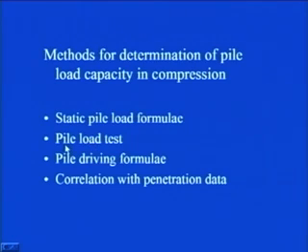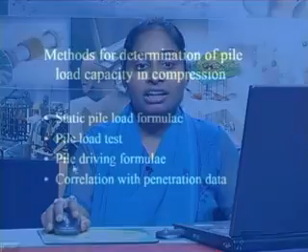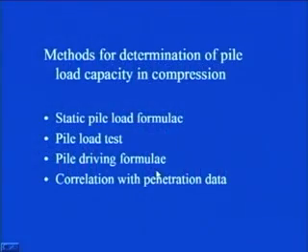Then by conducting a pile load test in the field: let us say you constructed a pile and there itself you test it and find out what exactly is the load that it is taking. Then pile driving formula: depending on what type of hammer and what type of motor you are using, depending on its efficiency and all other things, you can estimate the load carrying capacity of the pile in compression using the pile driving formulae.